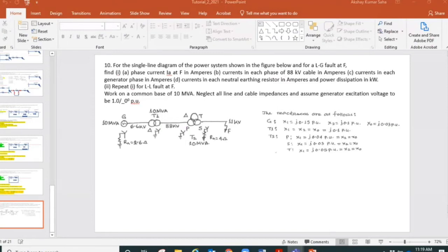Let's say I have two transformers, two winding transformers, I'm talking, not a three winding transformer. Now I'm talking about two transformers. One has its primary winding connected in delta. You understand primary and secondary better, so let me consider primary and secondary, but I personally don't consider primary and secondary. I will consider primary and secondary only when I have already connected it. Before I connect the circuit to a system, I don't consider them primary and secondary. I consider them as high voltage and low voltage. There is a reason for that.